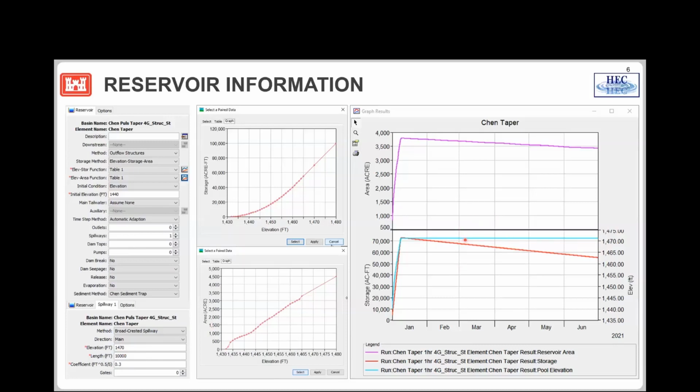In this case, you can see the blue solid line here. That's the elevation line. Elevation increases up to the spillway and then is steady. But before, with that steady elevation, the elevation area, elevation storage curve did not change. But now, based on the deposit amount, we can reduce the elevation area and elevation storage based on the deposit. That's the new result.